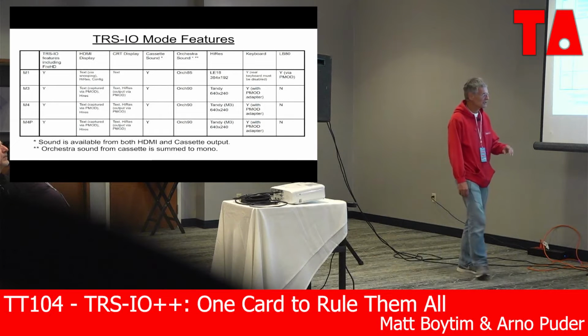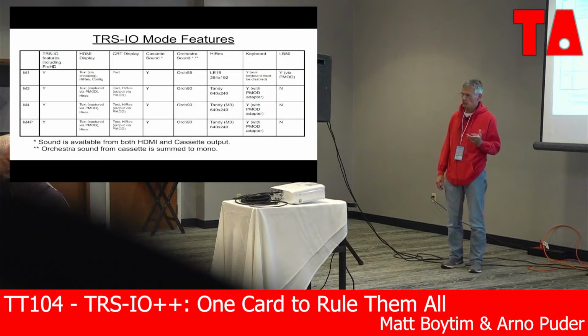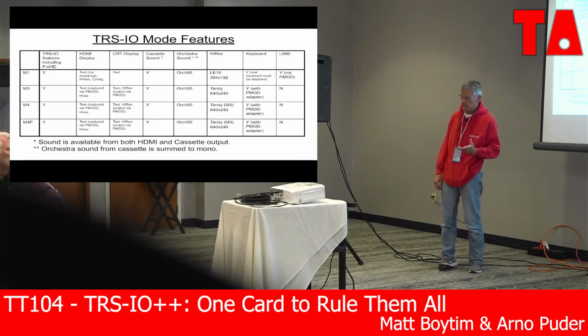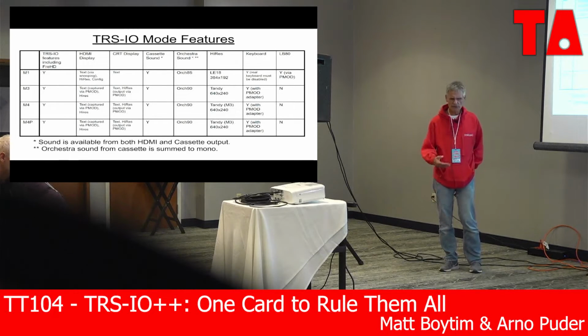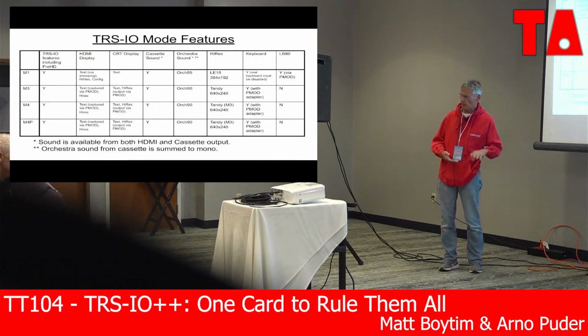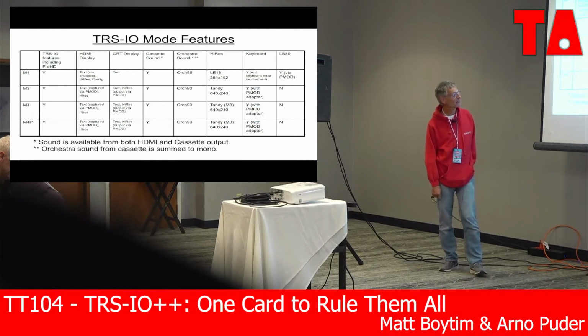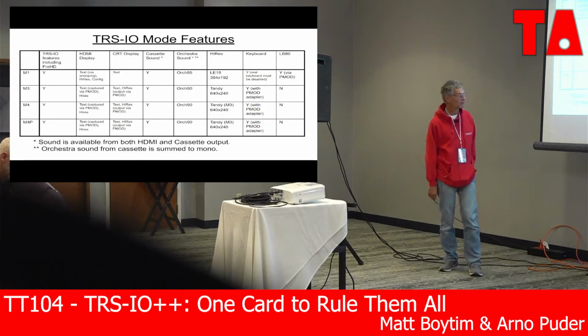The one limitation is on the Model 4, the high-resolution graphics board is internal, and we connect to the external bus. So we can't fully emulate, at least not conveniently emulate the Model 4 graphics. But we can do it kind of Model 3 style, where we're completely external, connected to the external bus. And then with the keyboard, we can also use the Pocket TRS keyboard connector to replace the keyboard on the machines.